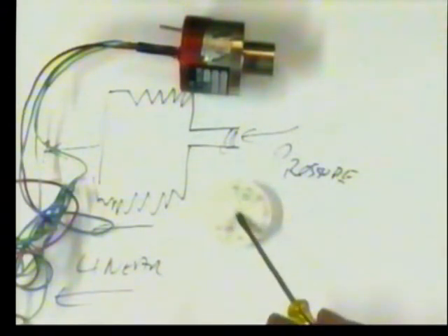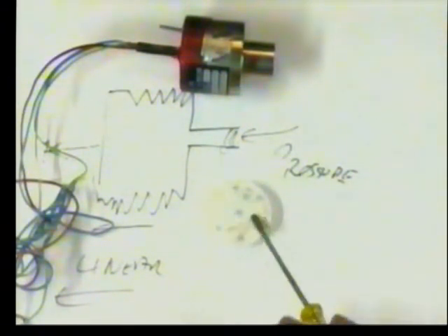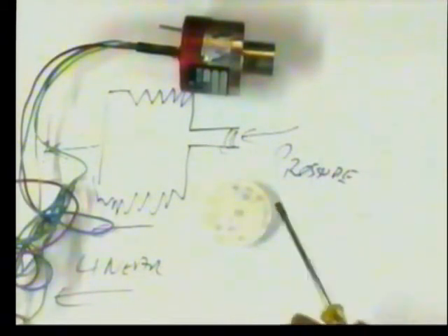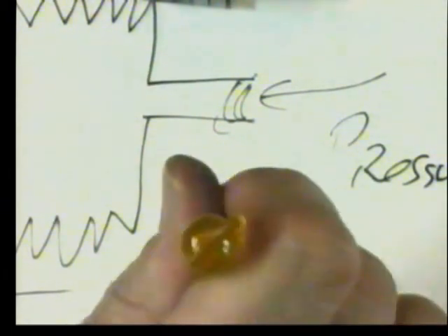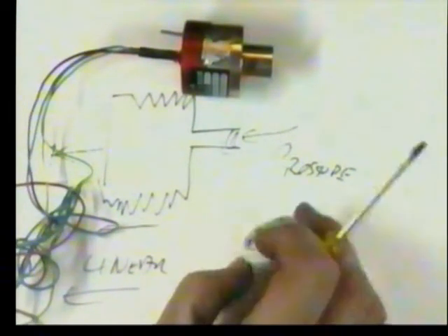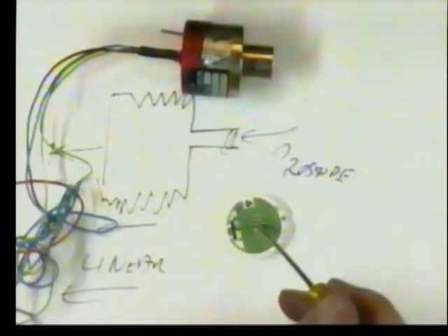Here's the actual bending member here. This is actually etched onto silicon. And when pressure is applied to this ceramic by pushing down onto the paper, that moves the bellows arrangement, which has been etched into, you can probably see some of the microcircuitry in there, and in here is all the signal conditioning required to convert that pressure into an electrical signal that is transmitted out. And here we can see the electrical contacts where you'll connect that off.